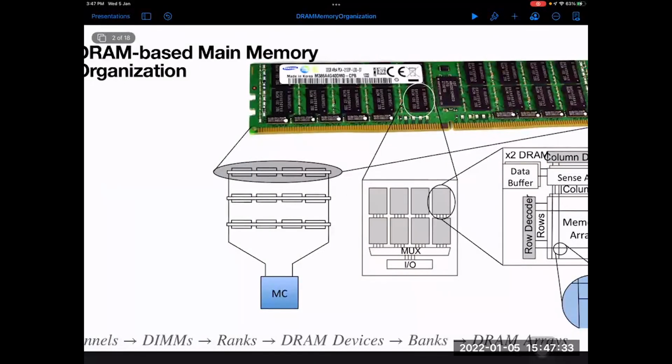So the middle chip actually takes care of this ECC part. And the DIMMs which are not supporting ECC, non-ECC based DIMMs, you will have an even number of devices and so on. But this extra one is actually taking care of this ECC. And most of the time they'll use either parity, even or odd parity, or SecDed type of things. Not highly complex error correction mechanisms. So basically the chips which do not have this ECC capability were more vulnerable to rowhammer.